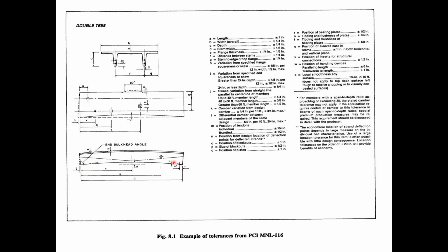And the reason this camber happens is because of the pre-stressing. So you've got this pre-stressed component. It's got some camber, and you take this double T out to the field and you set it, and then you put one right next to it that also has camber, but let's say the cambers between the two are different. Say the first one was 2 inches and this one's 1 inch. Well, now all of a sudden you've got a 1 inch bump.